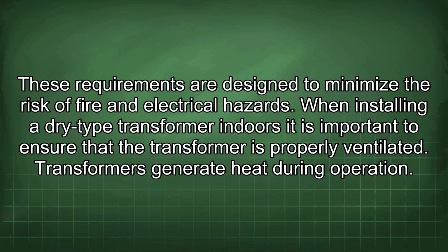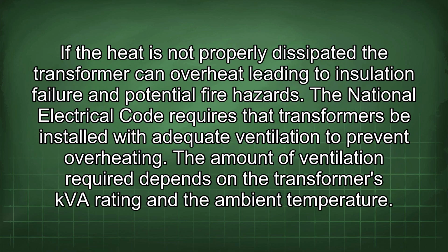These requirements are designed to minimize the risk of fire and electrical hazards. When installing a dry-type transformer indoors, it is important to ensure that the transformer is properly ventilated. Transformers generate heat during operation. If the heat is not properly dissipated, the transformer can overheat, leading to insulation failure and potential fire hazards.